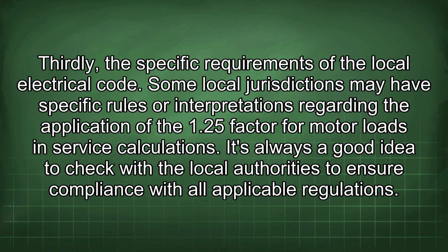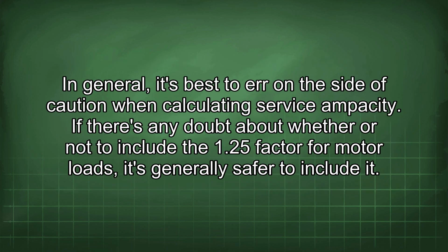Some local jurisdictions may have specific rules or interpretations regarding the application of the 1.25 factor for motor loads in service calculations. It's always a good idea to check with the local authorities to ensure compliance with all applicable regulations. In general, it's best to err on the side of caution when calculating service ampacity. If there's any doubt about whether or not to include the 1.25 factor for motor loads, it's generally safer to include it.